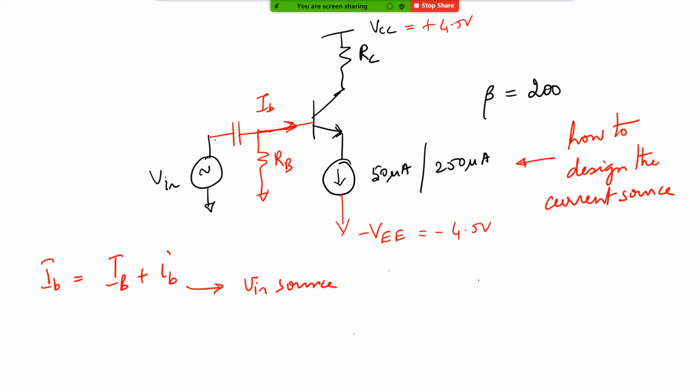If you take a microphone and you put some DC current through it, depending on the type of microphone, you can even damage it. Condenser microphones of course can handle it, but some of the other things cannot. Or if there are other sensors, it is not at all a good thing to push your bias current through the sensor or the signal source that you are trying to amplify.